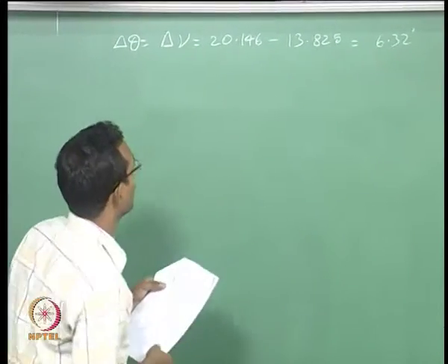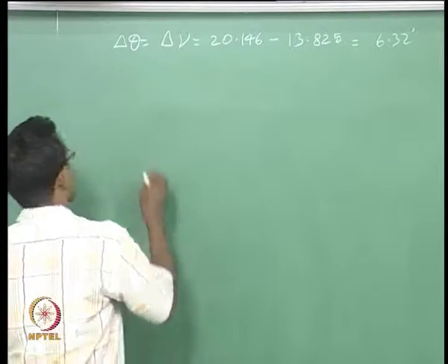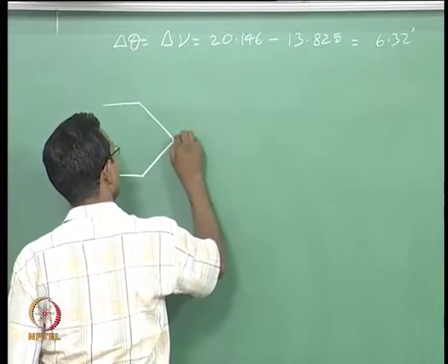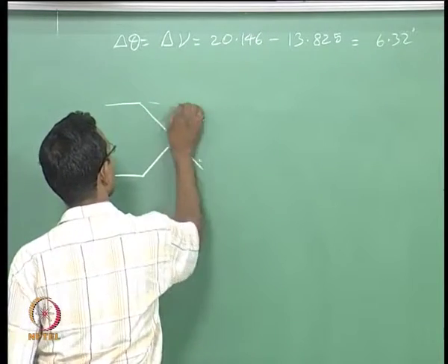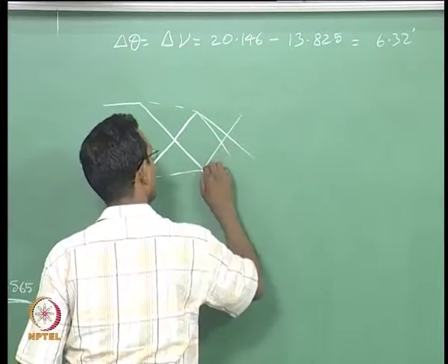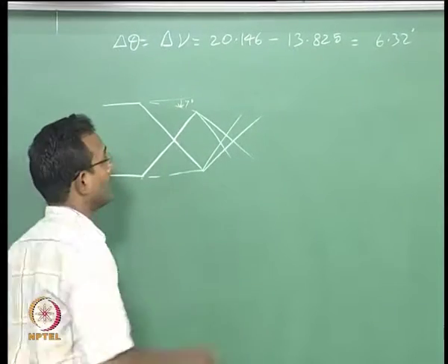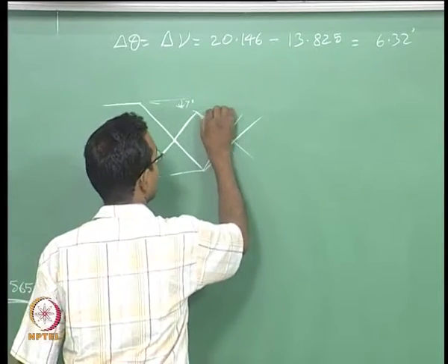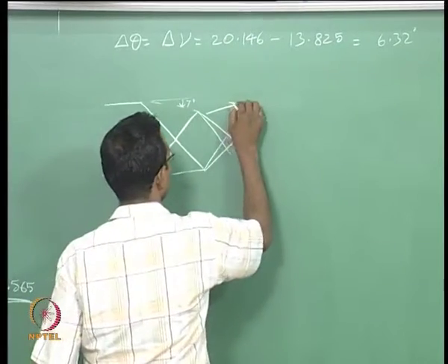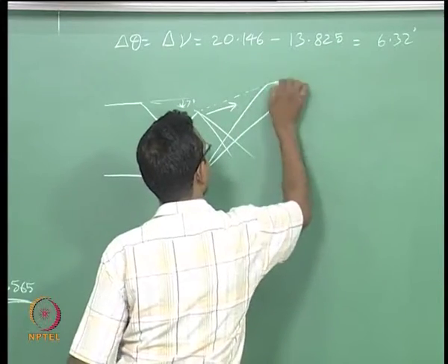Okay. You are having around 6.32 degrees there. So, if I draw my picture beyond that point, initially this turning angle was 7 degrees. Now, I am turning lesser, 6 degrees. Okay, it is not turning by the same amount, it is turning lesser, 6 degrees. And this expansion fan goes beyond that, after that we know.